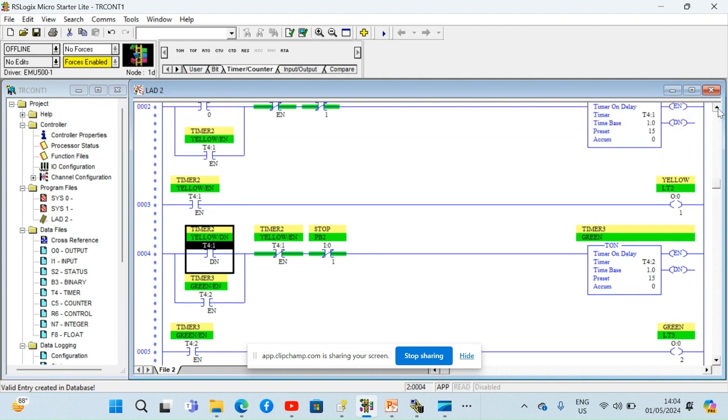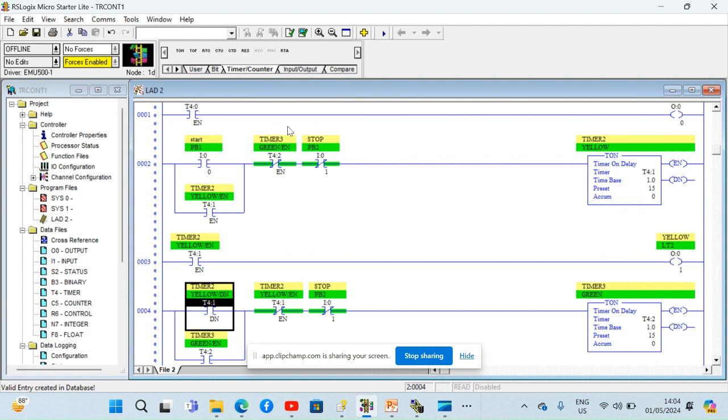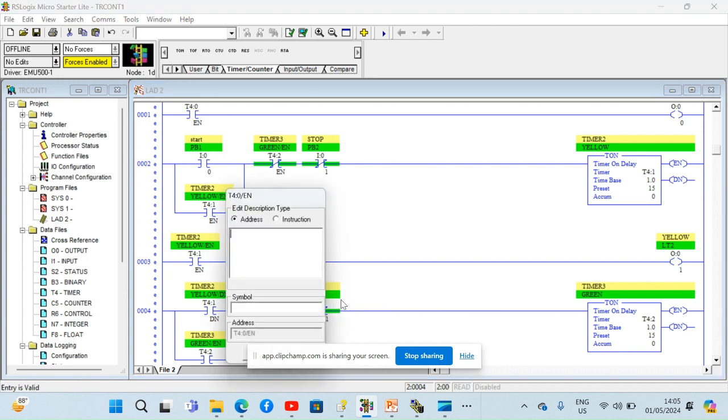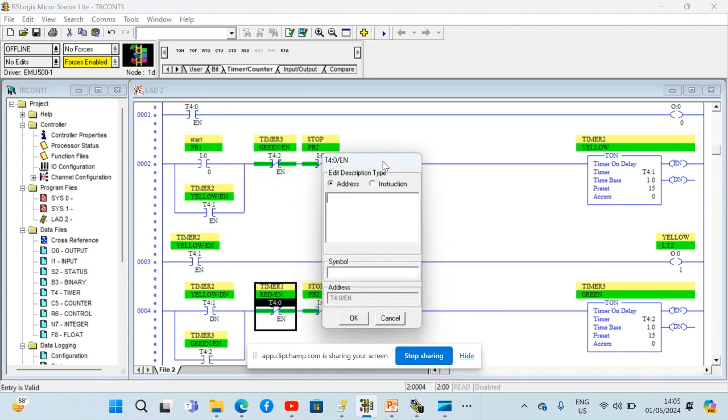So moving up back. Okay. So this should actually be set up by the first timer, not timer 2. It should be set up by the first timer. So I'll come here and change this one to 0. So once timer 1 comes on, which is coming on after this one because it's going to be in a cycle, this should go off. So I'll just give it OK.